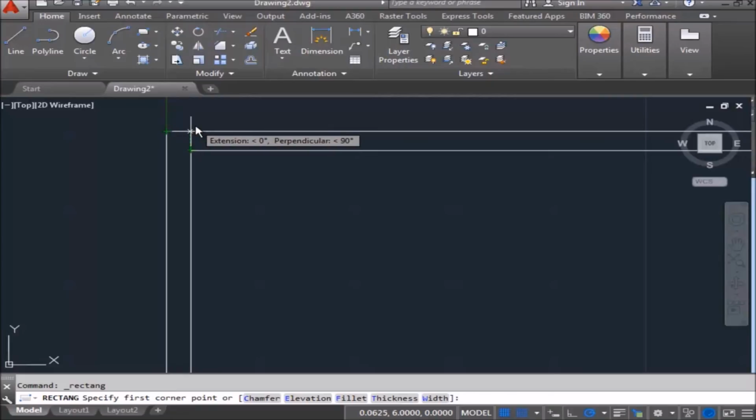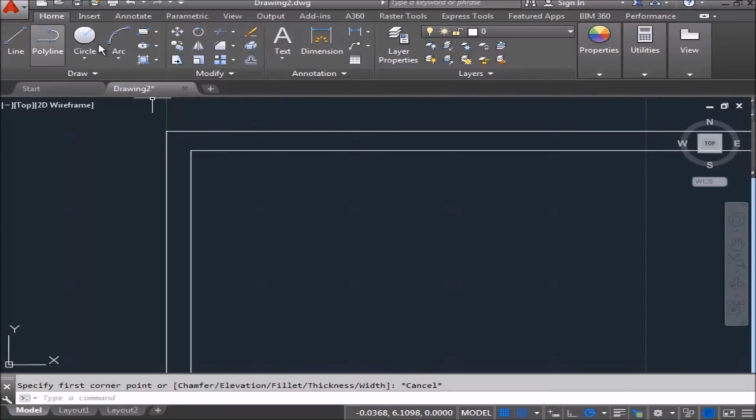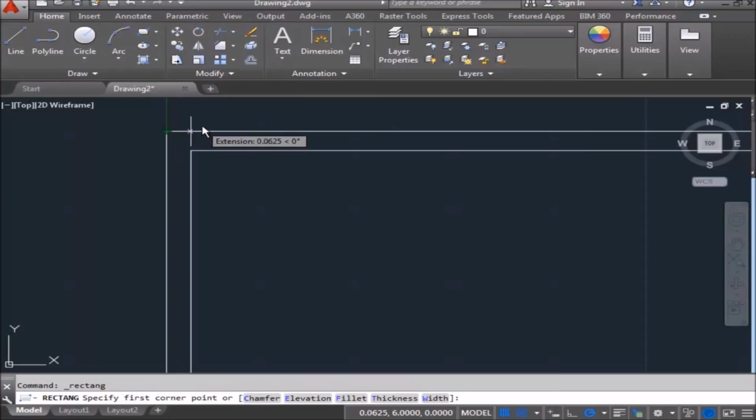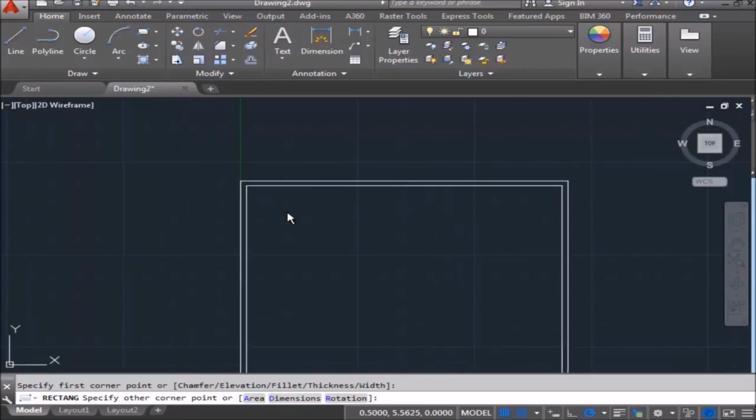So I'm going to go over until I find point 25 right there, based off the corner, and then I'm going to come down 25. So again, from here, I'm coming down a 16th to an eighth, to 3/16 to 1/4. So at this point, I'm going to click to begin my shape.